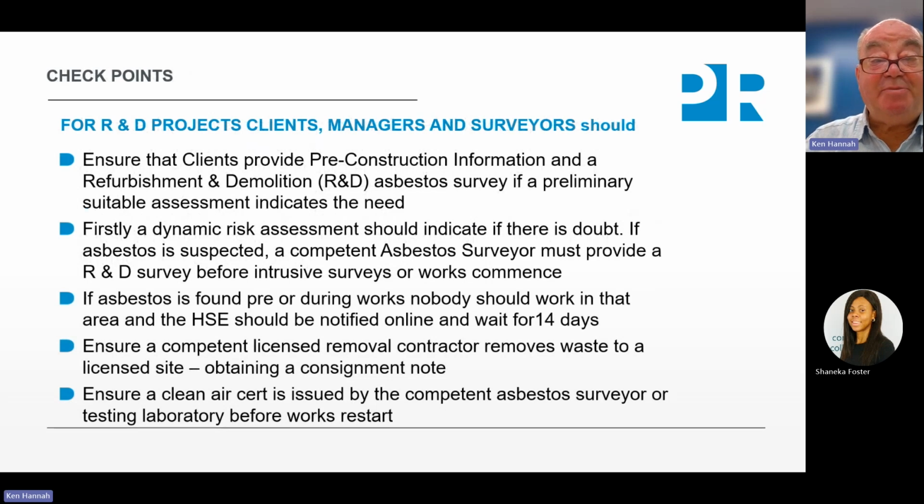For refurbishment and demolition projects, the checkpoints for clients, managers, and surveyors are that we should ensure that clients provide pre-construction information about asbestos in their asbestos register in the workplace, and the location of it and the type of it. And they must conduct a refurbishment and demolition, otherwise known as R&D, asbestos survey, if a preliminary suitability assessment indicates that the building was built prior to 2000 and is likely to contain asbestos-containing materials.